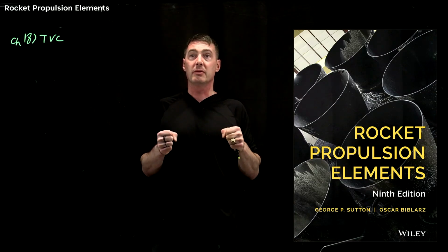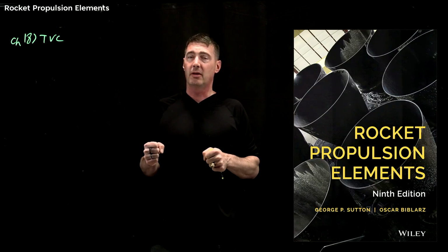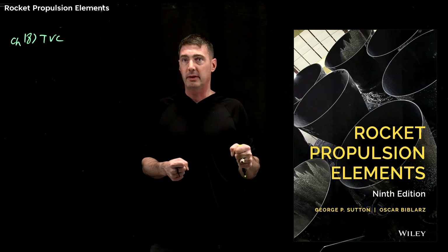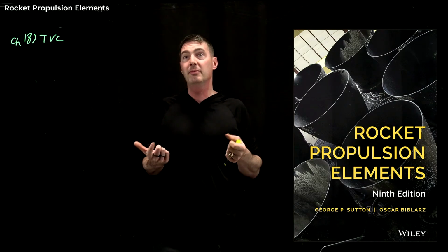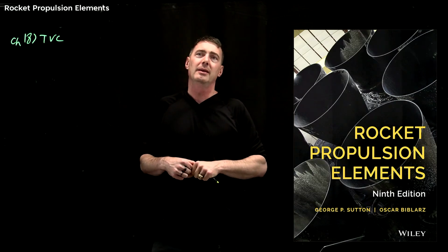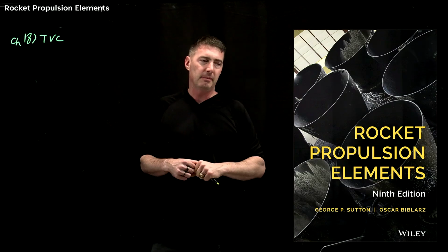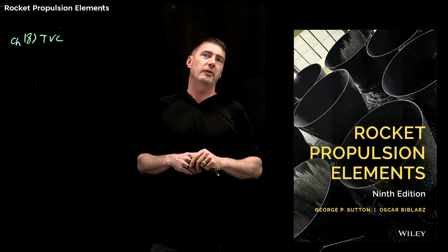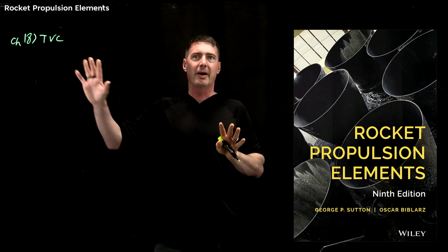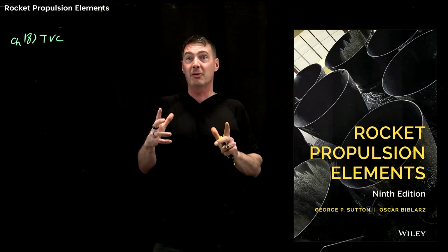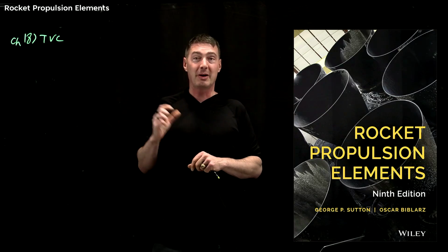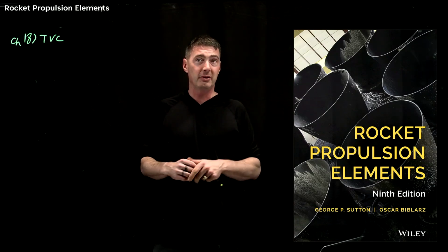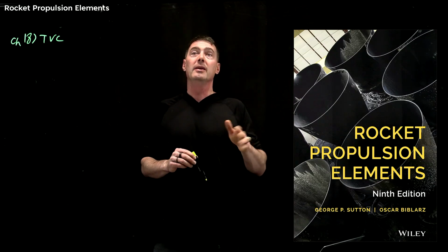Now sometimes it can be driven electrically. I believe Raptor engines are electric driven. At Virgin Orbit, our gimbal system was driven fuel hydraulically, so it was a hydraulic system, but using fuel, not hydraulic liquid. Those are the ones I'm used to in the rocket world, but certainly there are a whole other broad set. Again, I hope I don't do it on the video, I'm going to try really hard to call it thrust vector control, based on all the other flavors you can do to deflect the plume.